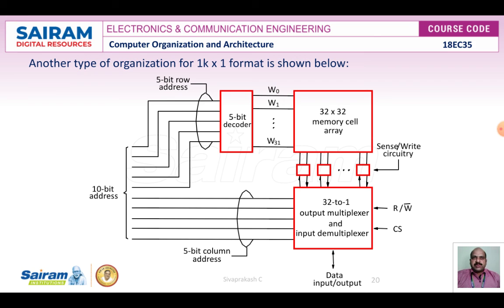Commercially available memory chips contain a much larger number of memory cells, so we use a small example to make the figure easy to understand. A large chip has essentially the same organization. We can also design our own, for example a 512k cross 8 organization, in which case 19 address lines and 8 data input/output lines may be needed. Chip capacities of hundreds of megabits are now available, which help us to come across more memory space.